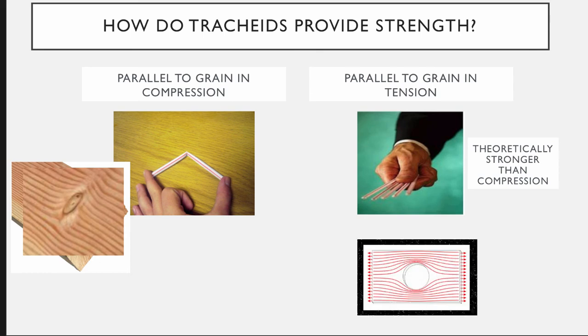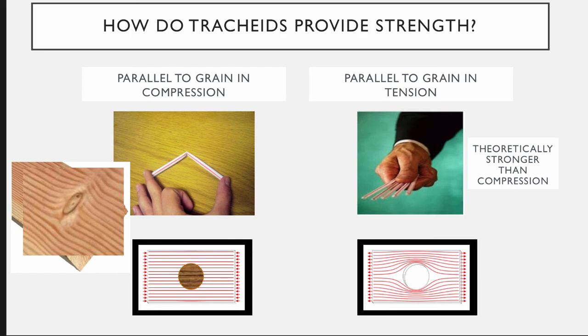Now, if you remember from strength of materials, if you have a member loaded in tension axially and there's a hole, the stress has to move around the hole. It can't pass through it, and you get a stress concentration. So it raises the stress that your member experiences, bringing you closer to the failure loads, even though you might not have a very high load. Versus in compression, we filled in our hole there with our knot of wood. If I push on that in compression, each side of that just presses against the knot, and the knot is able to transfer the load through. So it makes absolutely no impact in compression.